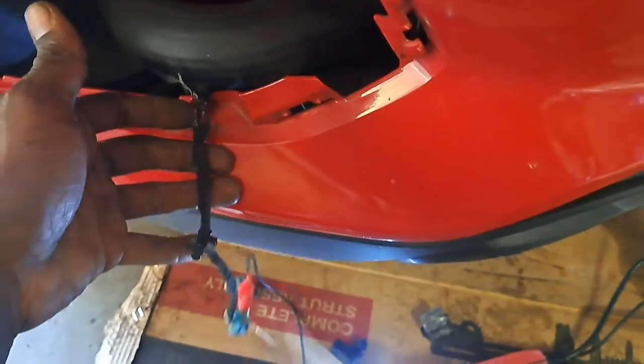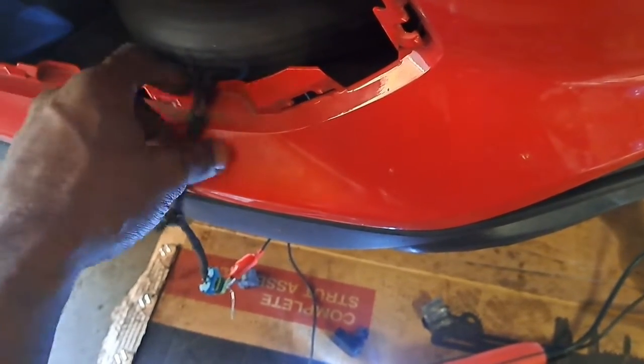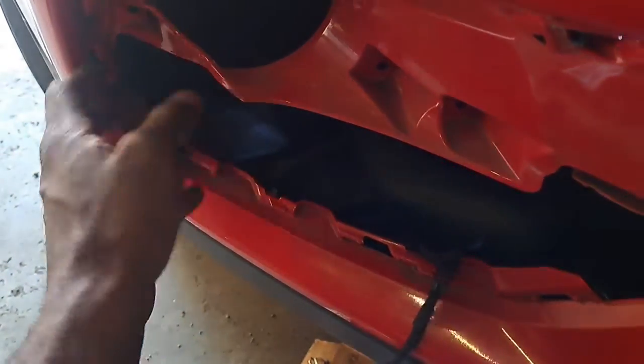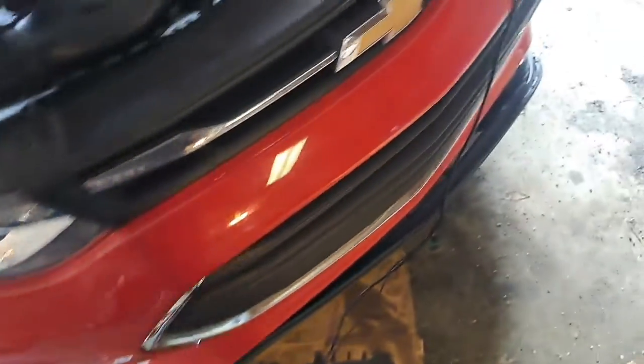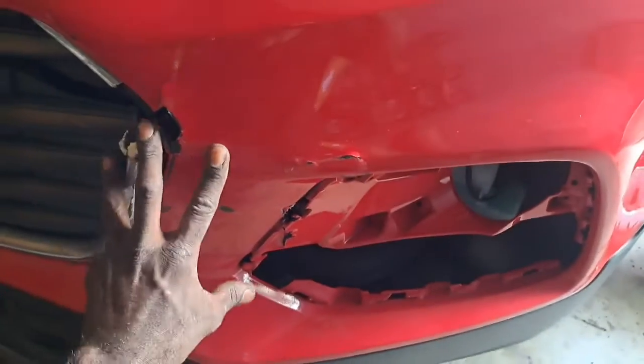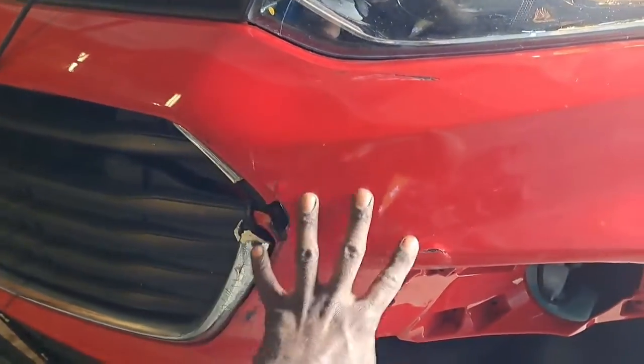I went about a foot back, checking for some sort of lack of continuity, and I tried to send voltage through that signal wire about a foot back, and it didn't change the PID data. I went about another foot back, nothing. But let me show you something. I need to go where the damage was. So if it was hit here, I followed the wiring harness from there all the way. It comes in this area here.